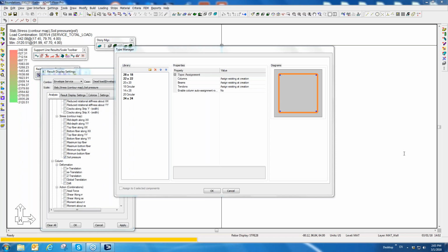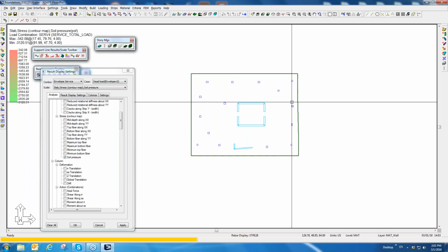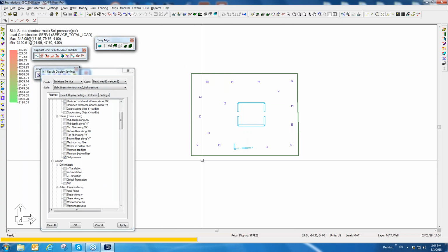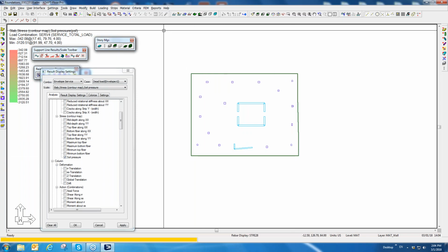The only way to do that, if you overlap a point spring and an area spring, the program will take the lesser of the two values and assign it to the node that the area spring is nearest. So if you want to mix the two, you have to use multiple area springs and point springs where you have the piles. I couldn't create an entire area spring.